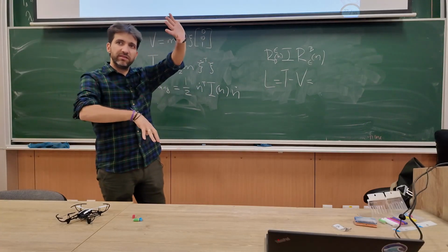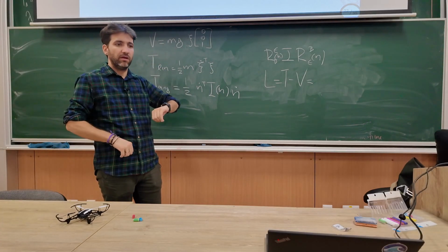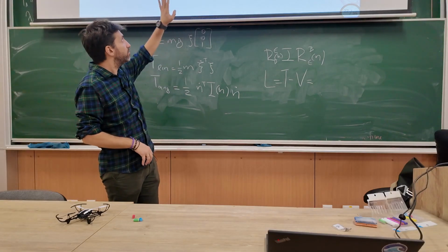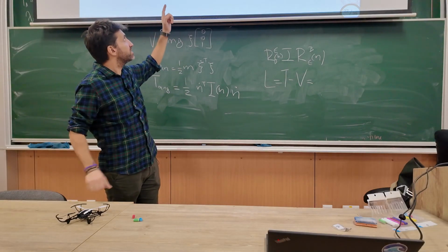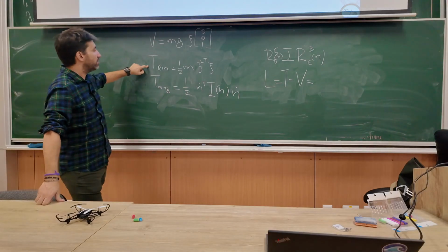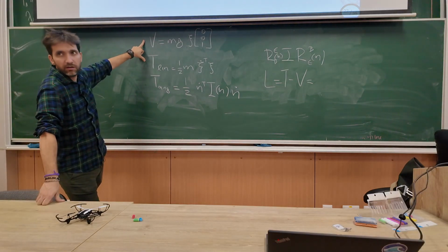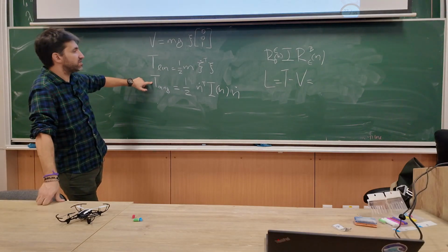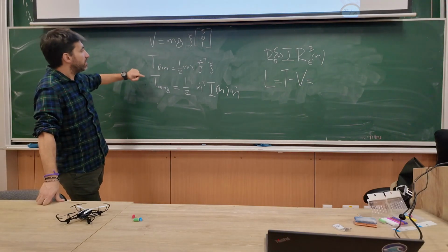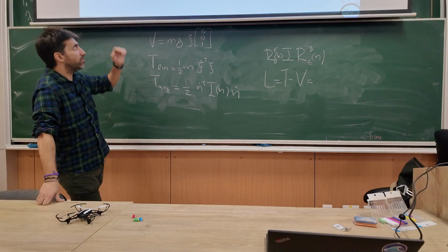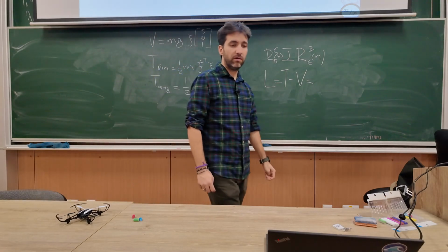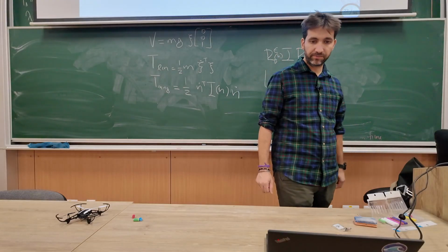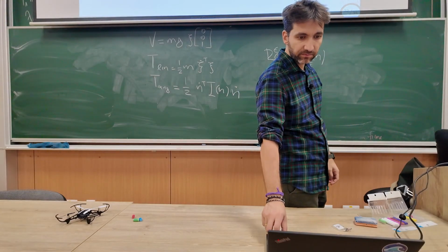So I can basically split this into two subsystems and have the linear part, which I will derive with xi, and I will only have the linear velocity and potential being affected, because the derivative of this with xi will be 0 and xi dot, and the angular part will be only affected by eta and eta dot. All right.